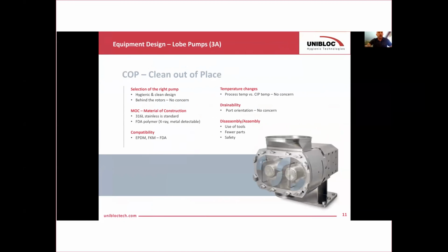Switching over to clean out of place equipment, you still want to find a pump that is hygienic and has a clean design. For example, the concern about getting clean behind the rotors, you don't have to worry about that anymore, since the rotors are going to come out, and you will make sure manually that you're cleaning out inside the pump.